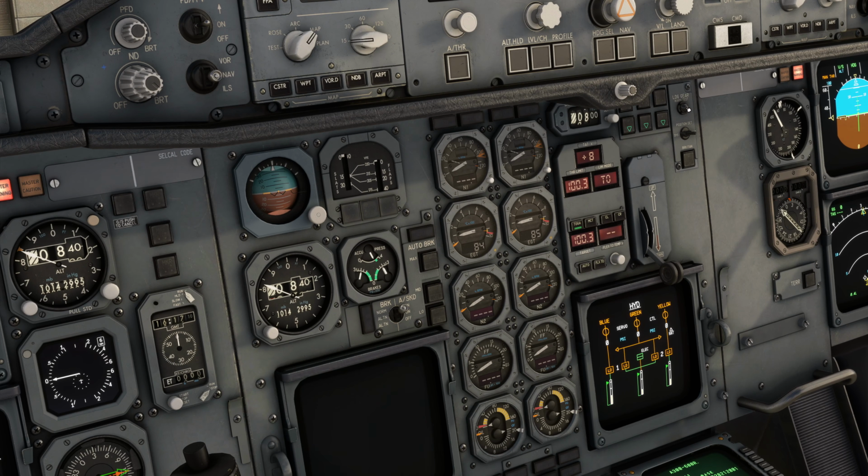Okay, moving on then, we get to our landing gear warning and we're going to execute the test. So press that button up here and we get the landing gear unsafe, landing gear position detection system 1 fault, and it wants us to select system number 2. Now that is all we need to do and we're done with this. The position detection itself is going to switch to system 1 when the captain is pilot flying, or system 2 when the first officer is pilot flying. So we're going to keep it on system 1. Going further down, the brake fan is switched off.